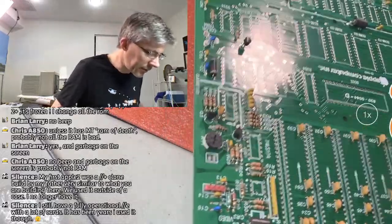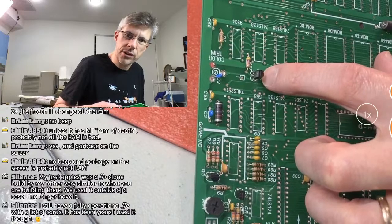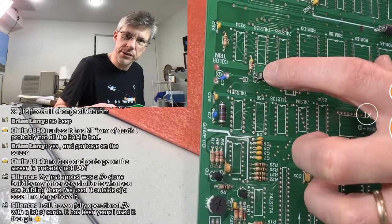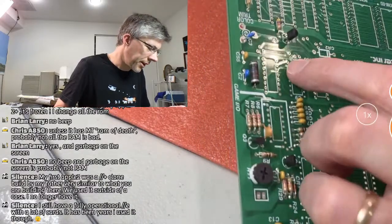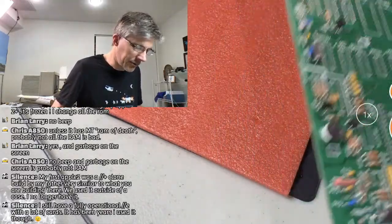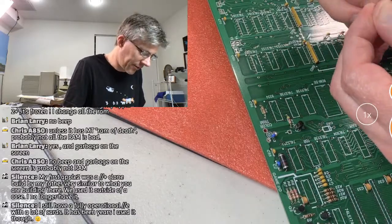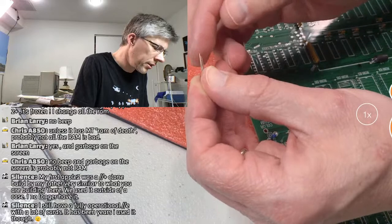Okay, so we've got that transistor in Q6, and then you can see that I've made sure to put the flat part of the transistor the same direction as the flat part on the PCB, so don't be like me and goof it up. And we'll go ahead and do the same thing for Q5.